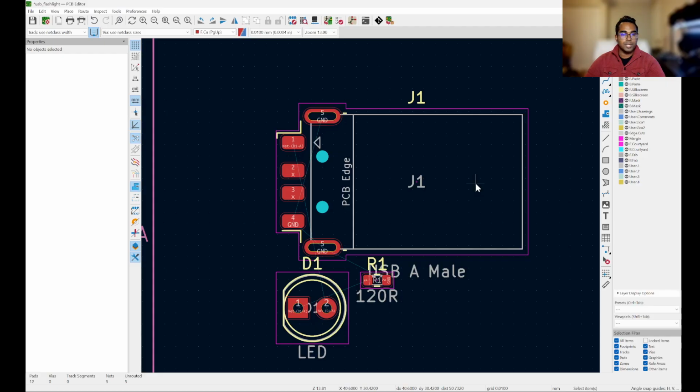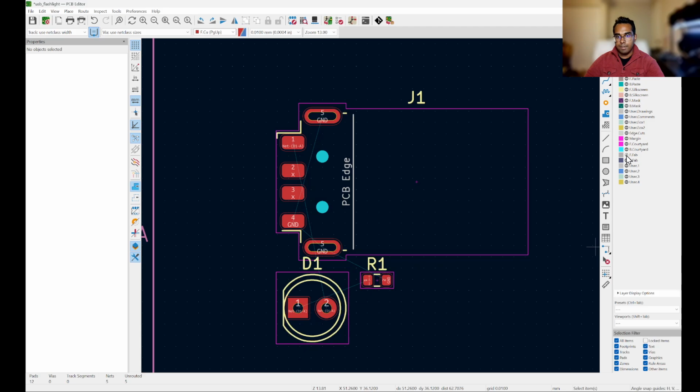It's not actually printed on the board and not actually used for any cutting of holes or etching of copper and so forth. So we can go ahead and hide those layers so we're not as cluttered. I'm going to click on the little eyeball icon right next to the fab layer right here, and you'll see that those vanish. This is much easier to make sense of.